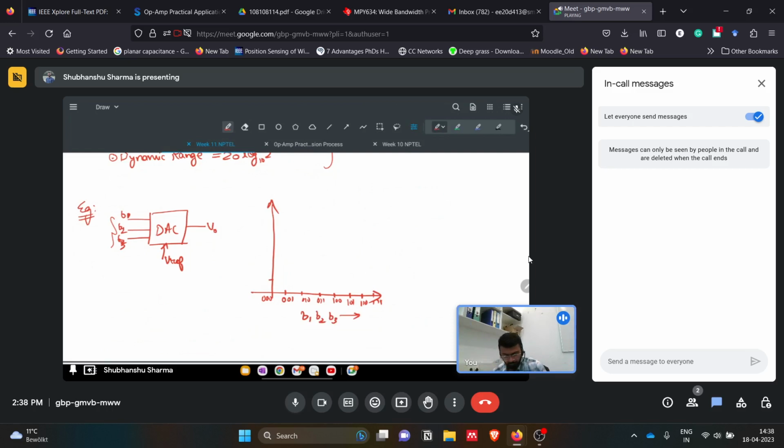So now another thing. We can have 8 bars for this, based on the resolution. By the way, the resolution is given by V full scale range divided by 2 to the power n. So this is the resolution for 3 bits. If the reference voltage is 1 volt, then it will be 2 to the power 3, that is 1 by 8.